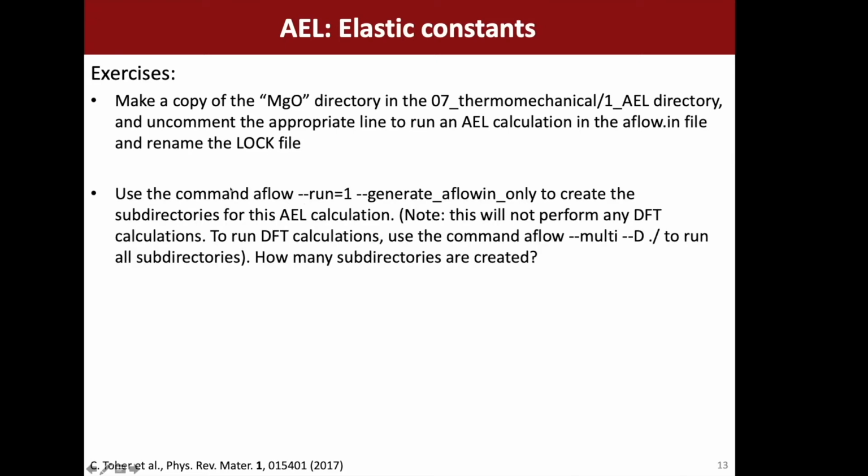Once you have this lock file, you can use this command, aflow --run=1 --generate_aflow.in_only, to create the subdirectories for this AEL calculation. We only need this flag at the moment because on this virtual machine we don't have access to VASP.